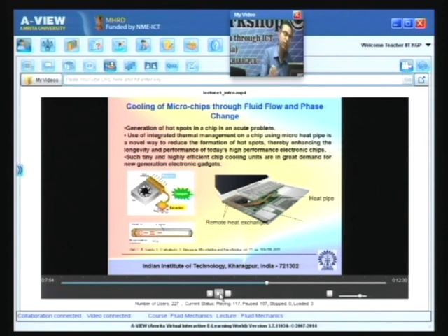I can give you one or two examples of how this can be done. You can employ something called a micro heat pipe. So, what is this? You have a device where there is a liquid, the liquid takes heat from the heated device and gets evaporated. After it gets evaporated, there is a fluid flow because of capillary pressure.